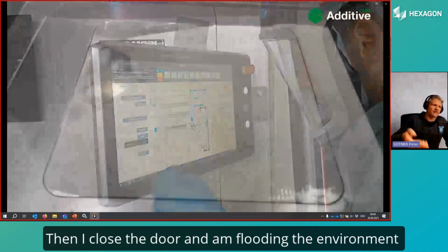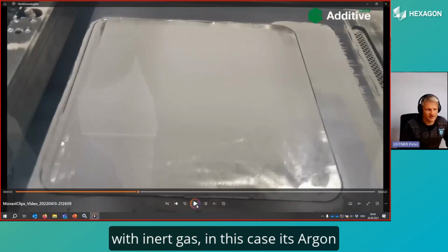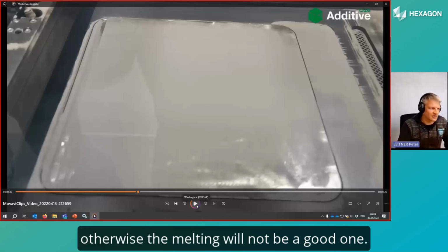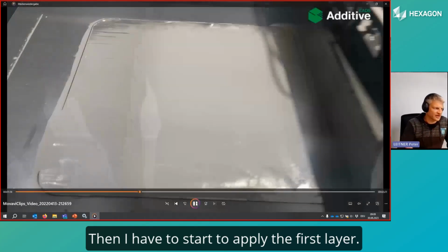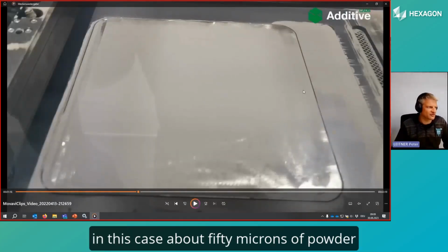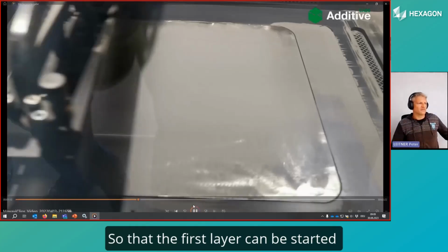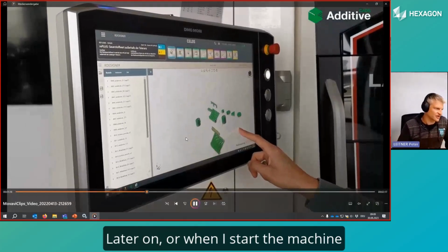Then I close the door. I'm flooding the environment with inert gas. In this case, it's argon, to have an inert environment, because otherwise the melting will not be a good one. And then I have to start to apply the first layer. So a bunch of loosened powder, in this case about 50 microns of powder, is applied to the base plate, so that the first layer can be started later on, when I start the machine.